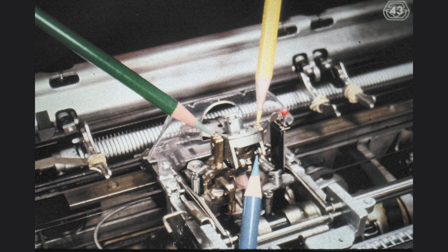After you have removed all the indicated items, you should half-cycle a print operation for any character, and the tilt ring will readily come out of the yoke. As mentioned, the yoke is the part which has the two arms indicated by the green and yellow pencils. The yoke supports the tilt ring. Be sure to use the correct Bristol wrench for the set screws indicated by the green and yellow pencils.